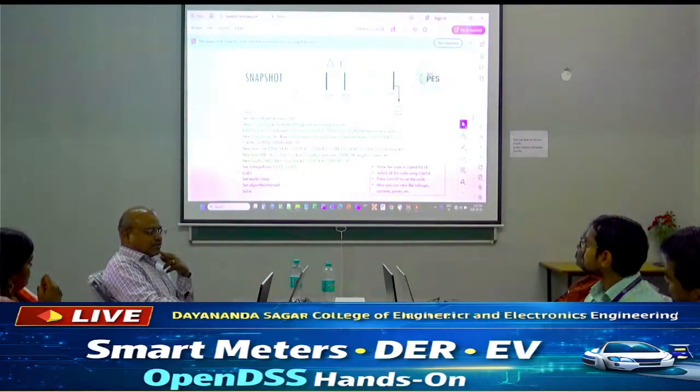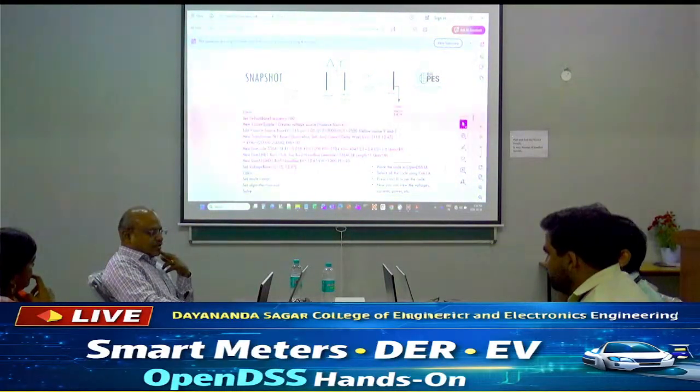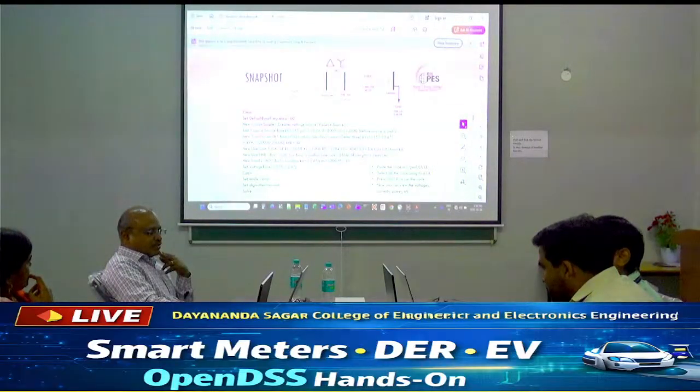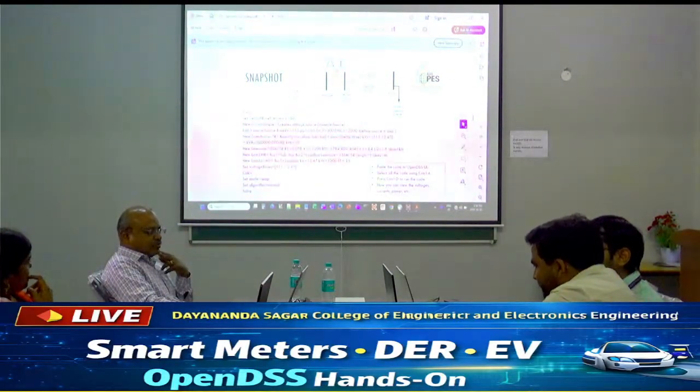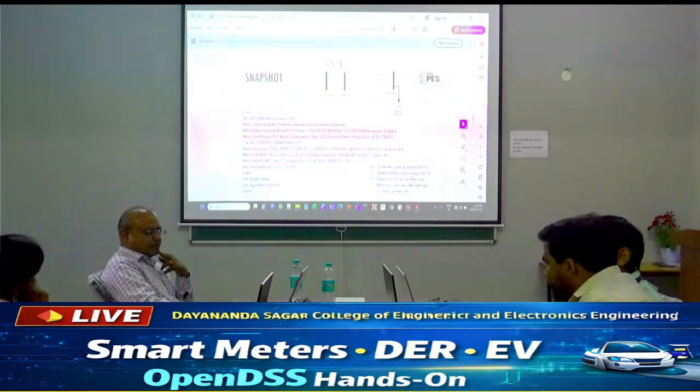So now there are two buses, the source bus and the sub bus. Now you are defining the transformer. It's a delta Y transformer. You say transformer, the buses are source bus on this side, and the name of the transformer is TR1. So source bus and sub bus.